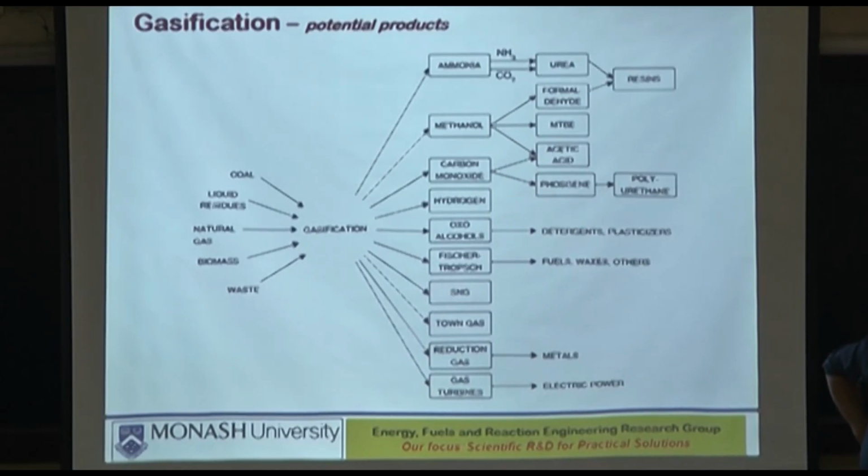Because yesterday I said pyrolysis starts quite early, right? In the pyrolysis process, majority of the methane is released. So methane will be released quite early, well before gasification starts, at 400-500 degrees. And gasification doesn't start until 800 anyway. So methane is a fact of life. It will remain all the way through, whether you like it or don't like it.